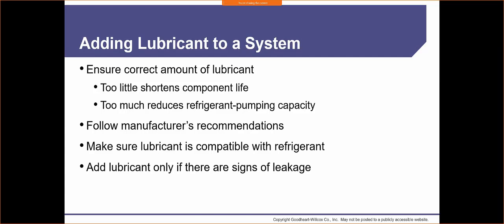All right, so if we find a leak on a system and some of the mineral oil is spewing out the side, does that mean we just run back up there and throw a bunch of oil in to help the system out? No. First off, if we can fix the leak, we will. Secondly, how much oil did we just shoot out? I don't know. I don't think there is a way to know. You'd almost have to tear apart the system, pour out the oil, weigh it, pour it back in. Is it worth it? No.